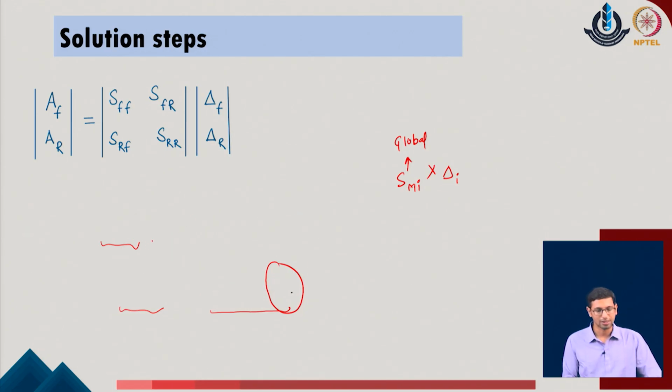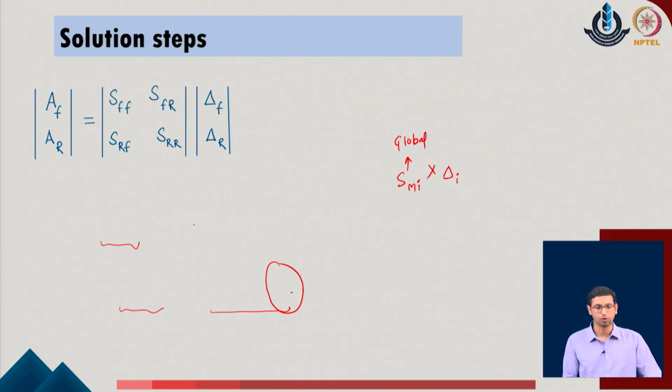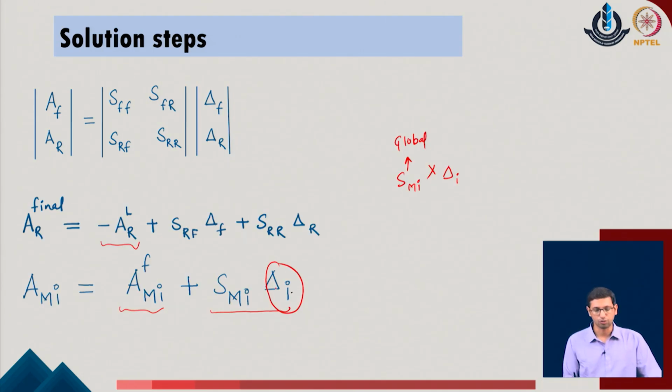So, the delta F which we have obtained in the given problem, once that value is known to us, delta R which is also defined already at the beginning, which means all the restraint values, we arrange all of them in the order of the standard degrees of freedom in the given system, and that becomes the delta. Out of those we will pick specifically those values which correspond to the delta of I, which is the ith member of the given system.